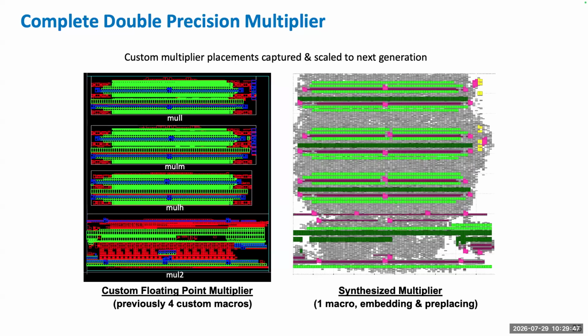So this is a multiplier on the left that I did pretty much in a semi-custom flow with some full custom components in there too. Many years ago when I first joined IBM, it took maybe a year. And then this is a nearly comparable version of it, which took maybe a couple weeks. In going through these designs myself, I realized that yes, you can get high quality, but the pain is maybe not worth it. So let's do something that is efficient. And furthermore, we get more trial effort, so I can try more experiments. I'm not locked into one design point for a long time.